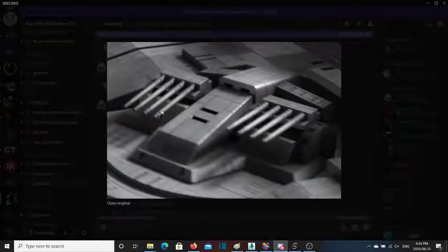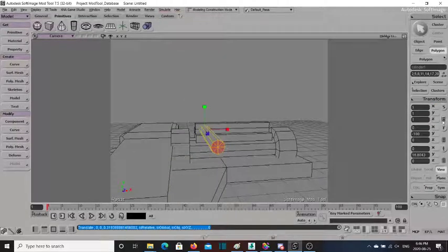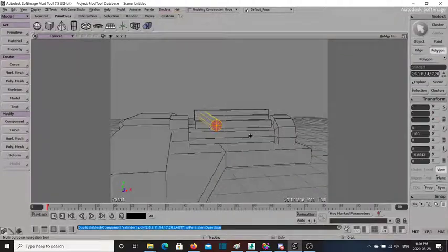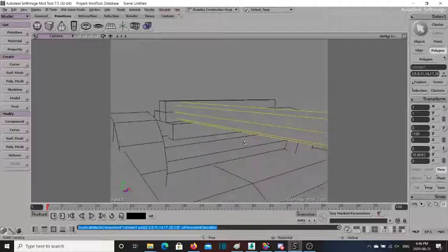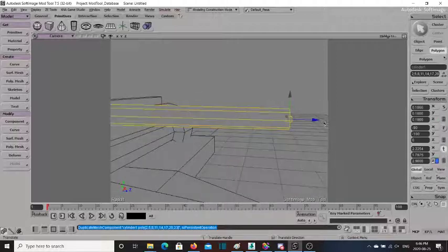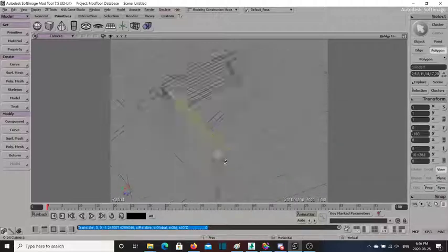Right. Now there's these little rings here, and I know that you're trying to do the details here. This can all be done with a normal map later, so can all these lines. Don't make a highly detailed geometry, because you're going to make it harder on the game engine. So all that we're going to do is extend this outward. We are then going to scale it along the X and Y axis to make it slightly tapered. Control D to extrude the edges that we have, and we are going to scale those inwards, Control D, and now we move it along the Z axis to make a nice little barrel, and that is it.